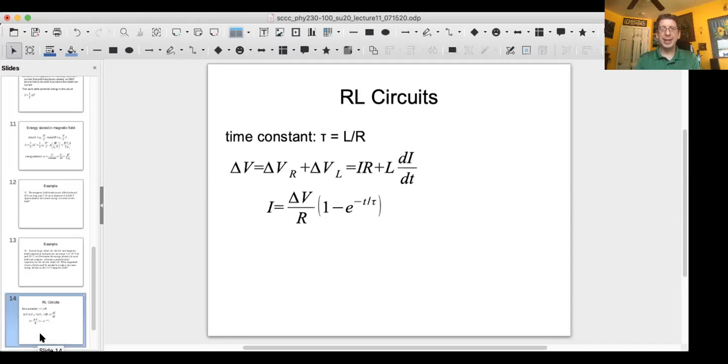Keep in mind from this, inductances tend to be less than 1 Henry, and resistors tend to be quite a bit more than 1 ohm. So in a typical RL circuit, you've got a pretty small time constant. Usually you need to refer to the oscilloscope if you want to see the process of current building up as a function of time. It's not something that's easy to observe in real time, unless you've got a piece of iron that you can stick inside the conductor.